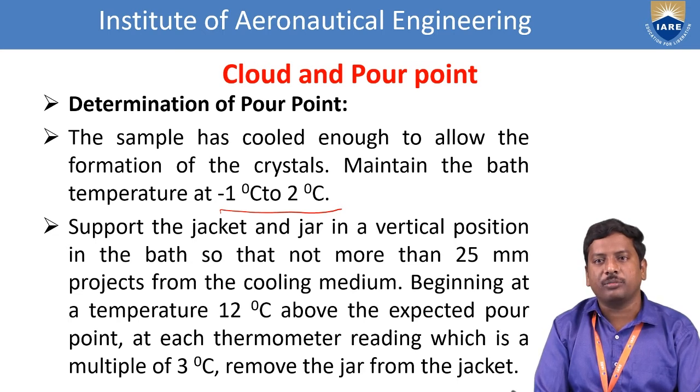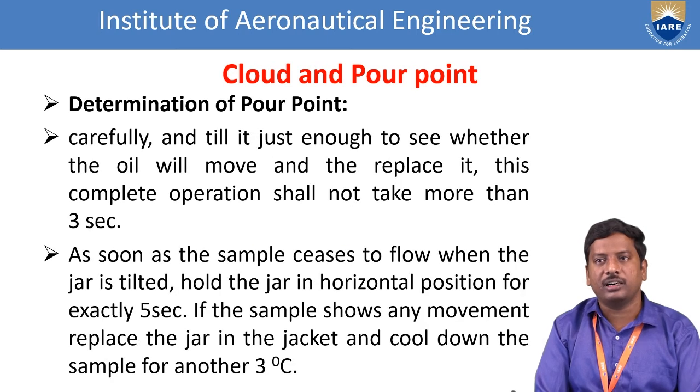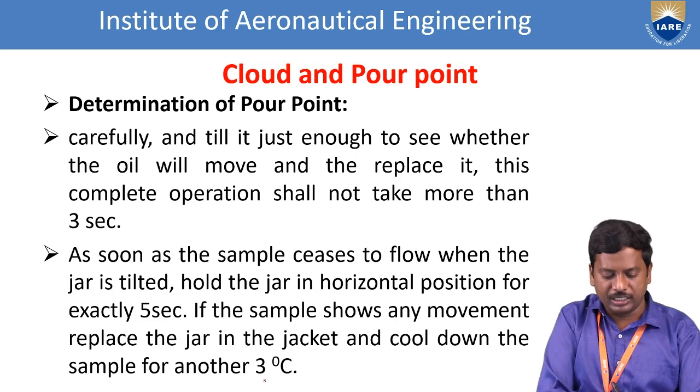now remove the jar from the jacket and tilt it carefully, just enough to see whether the oil will move, and replace it. This complete operation shall not take more than 3 seconds. As soon as the sample ceases to flow when the jar is tilted, hold the jar in a horizontal position for exactly 5 seconds. If the sample shows any movement, replace the jar in the jacket and cool down the sample for another 3 degrees centigrade.